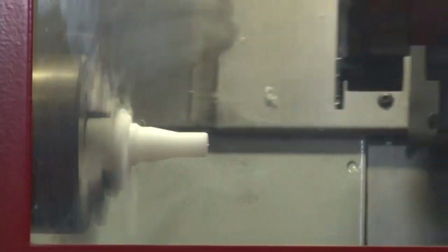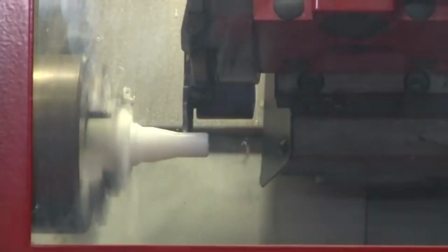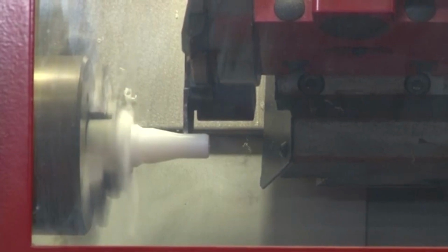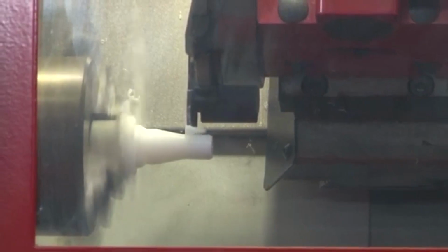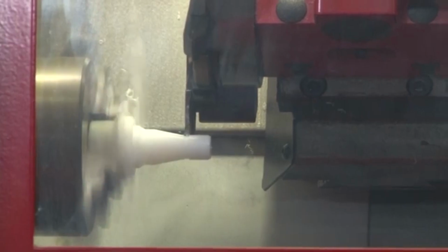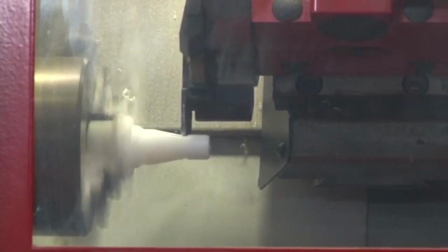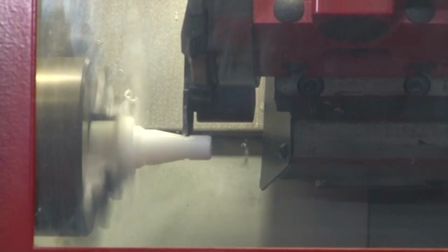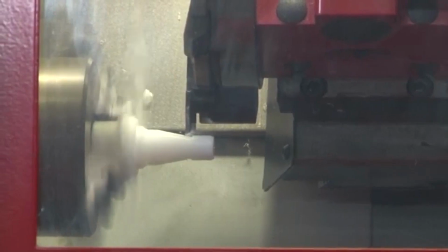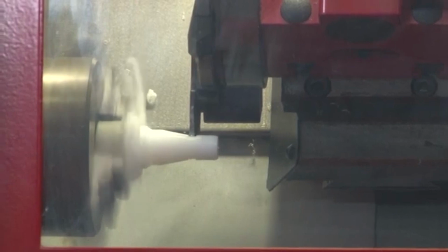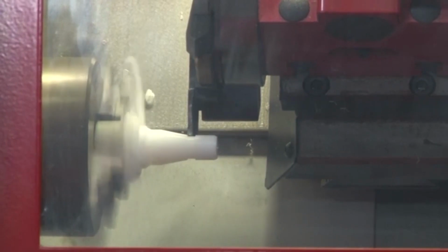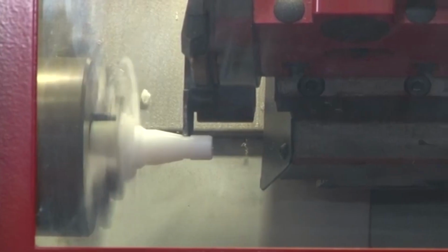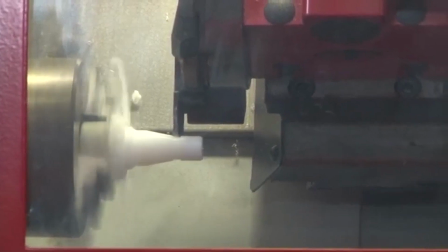Then another tool is coming. This is for the grooving. So, there is a grooving tool, and the program has been given in such a way that the grooving tool has to come there, and without the intervention of any human being, according to the program, the grooving tool is selected. It will come to the position where the grooving has to be made, and then feed will be given as per the value which is given in the program.